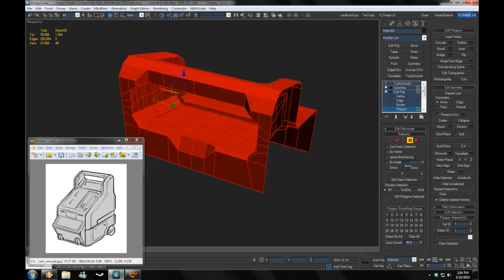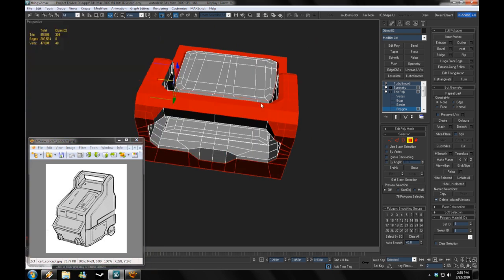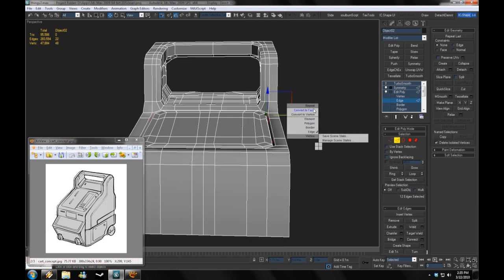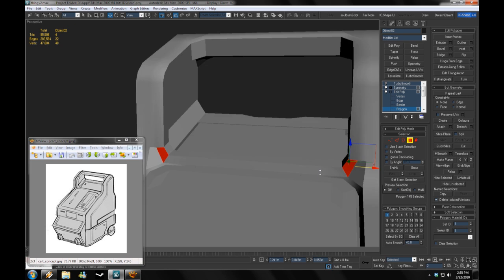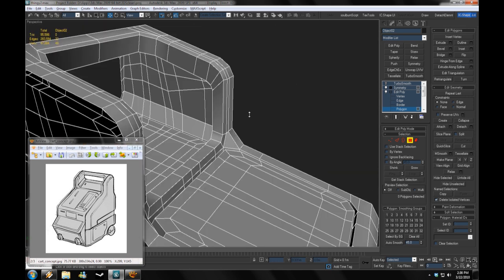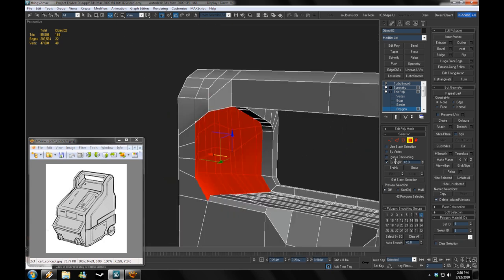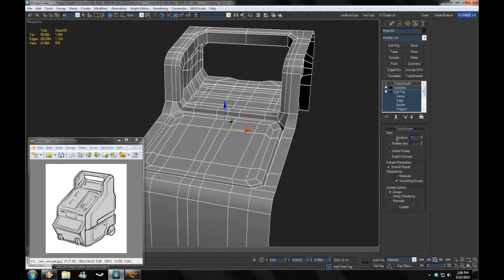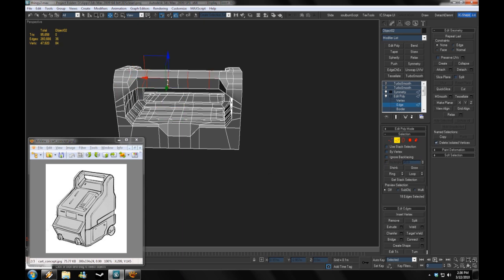So I'm going to be doing this thing, I guess you call it double smooth. That's what I've been calling it for a while. Basically what you do is you make your mesh really dense and then you put your turbo smooth on so that you can get those nice edge bevels really quickly. I like to do it with smoothing groups and using the turbo smooth by smoothing groups option. So what we can do is add in and keep shapes hard looking without manually defining edge loops, which will speed things up quite a lot.